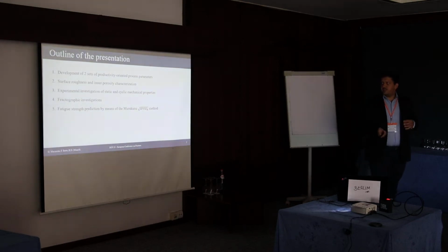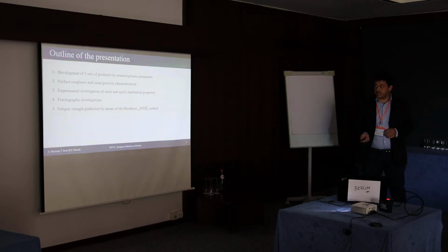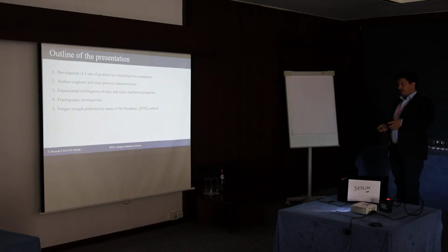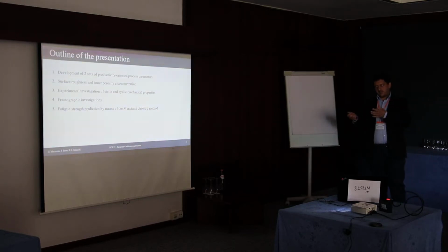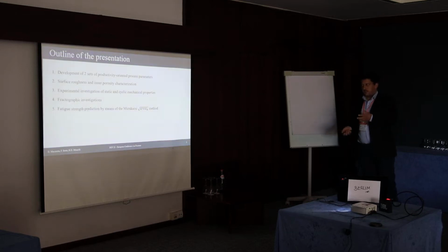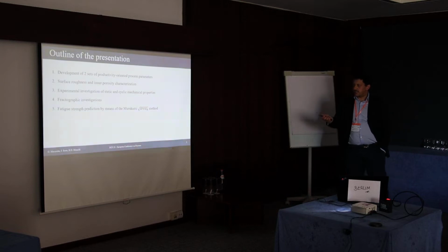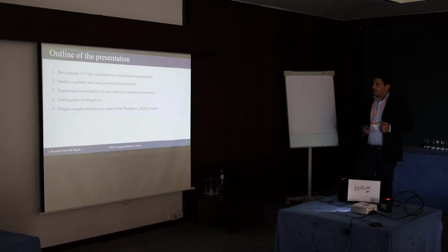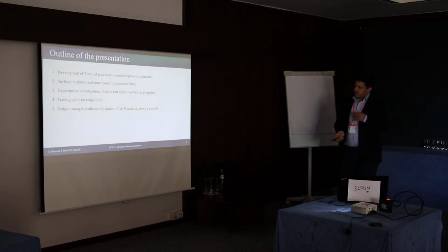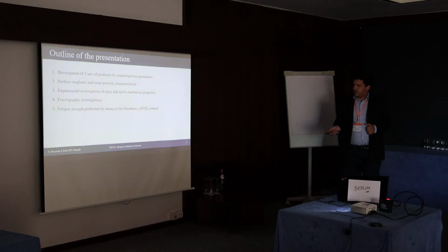The outline of the presentation. We'll see the development of two sets of productivity-oriented process parameters. We'll see the effect that they have on the surface roughness of the specimens produced and on the inner porosity. We'll see our experimental investigation on the static and cyclic mechanical properties. We'll see the fractographic investigation after the fatigue test, and we'll see an attempt to rationalize the fatigue data that we have within the framework of the area method proposed by Professor Murakami.